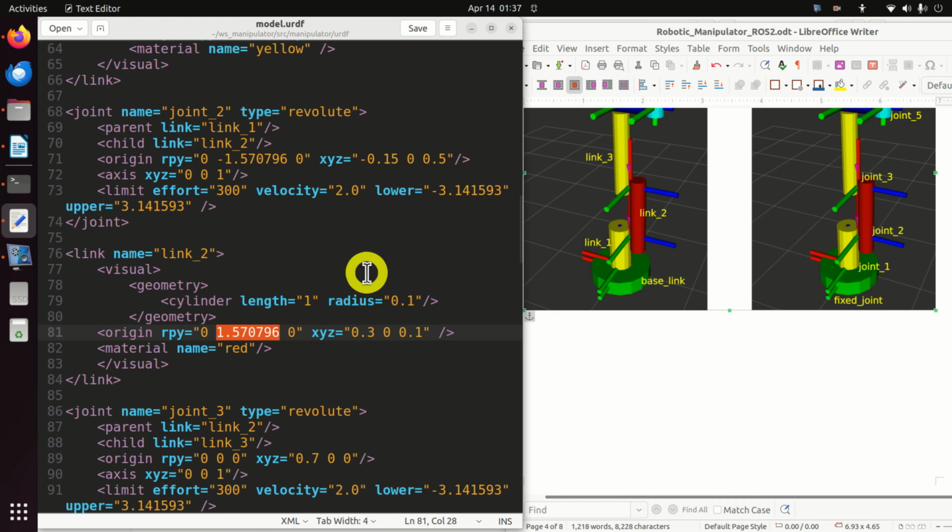Well, when you define a link, the link will automatically be extruded in the direction of the z-axis. That is, if you didn't have this rotation, this link 2 would go in this direction. The link would be along the z-axis, similarly to link 1 that goes along the z-axis. Consequently, you need to introduce this rotation. And over here we specify the color. The color is red, and we end the visual, and we end the link.